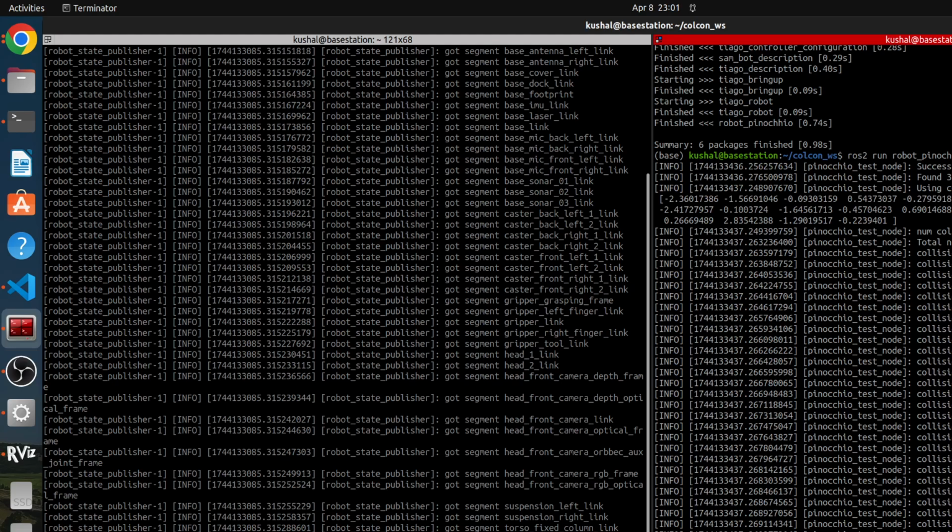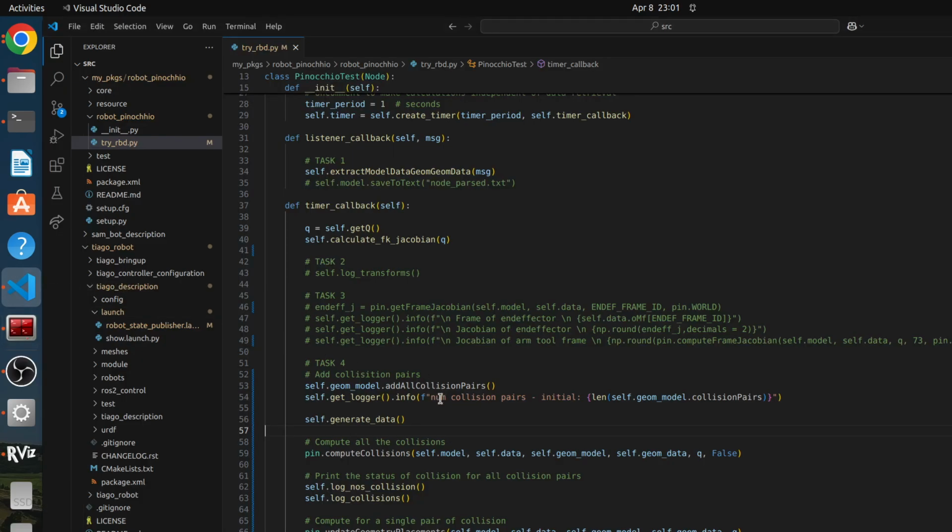So ideally we would want that any sort of issues with the URDF that is causing it to portray a self collision, we are able to remove that before calculating it, so that for any other forms of collision, if even one of the collisions is true, then the robot is in collision, and that will be used later on in the project.